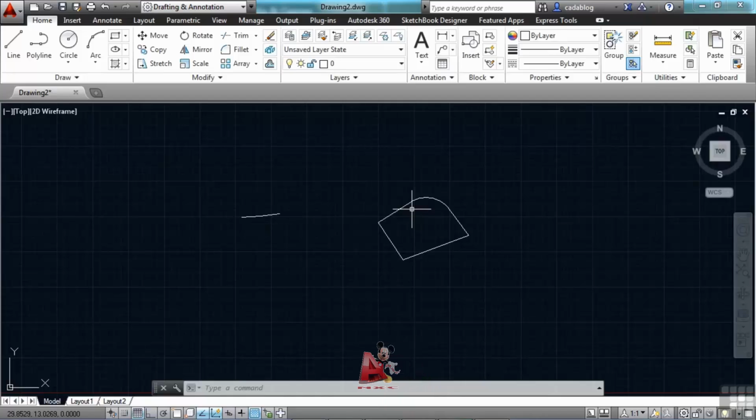Another thing that you can do is use the convert PSTYLE command. That's a long system variable and it's a command, but it lets users convert the current drawing to either a named or color dependent plot style. That's just a different way of managing your layers and line types and layer colors and line thicknesses when they print. If you're going to use a CTB file or an STB file, this is just something that will do that change for you on the fly.